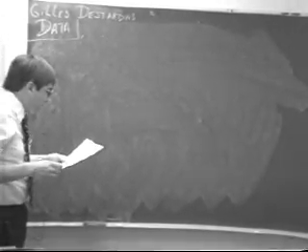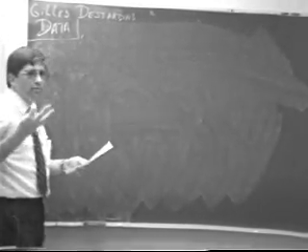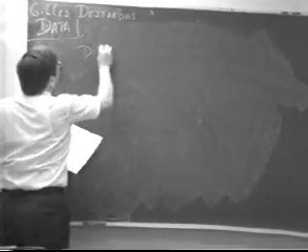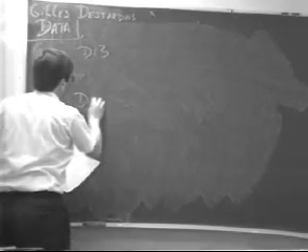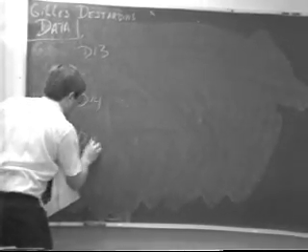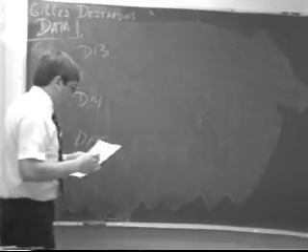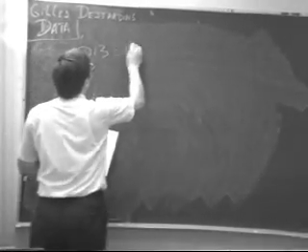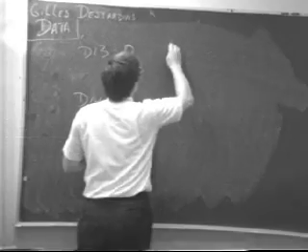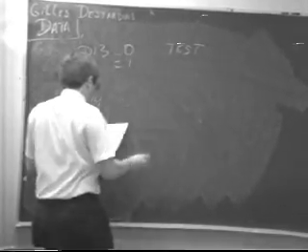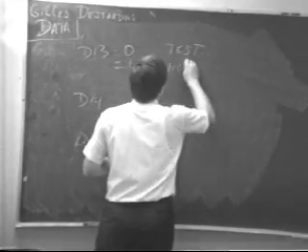Okay. The command register needs 3 bits, which is D13, 14, and 15. Depending on if they're high or low will mean a different thing. If D13 is low, you are in test mode. If it's high, you are in normal mode.